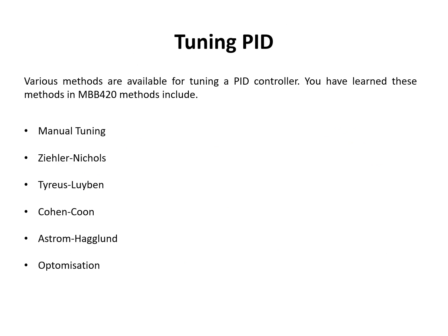So how do we tune the PID? There are manual approaches. You can simply tune the controller and see the response, and from the response you would have an indication of what should be done to the controller gains. Generally a very competent controller designer can do this by simply looking at the response and dictating what should happen to the gains. The advantage of this is obviously you don't have to develop a control system or a plant. You don't have to model the whole plant of the system to develop the controller.